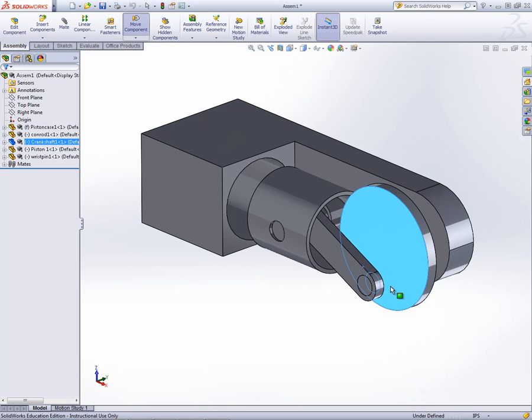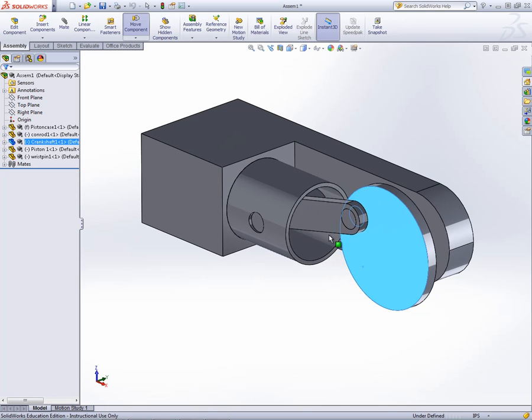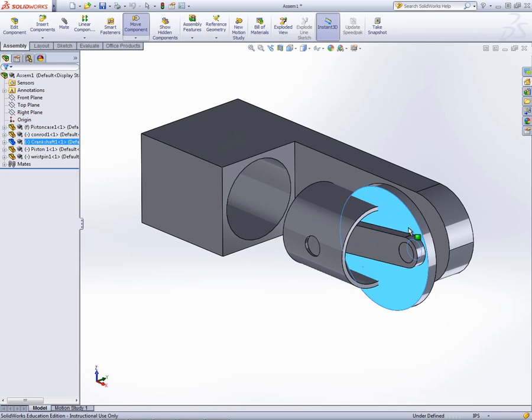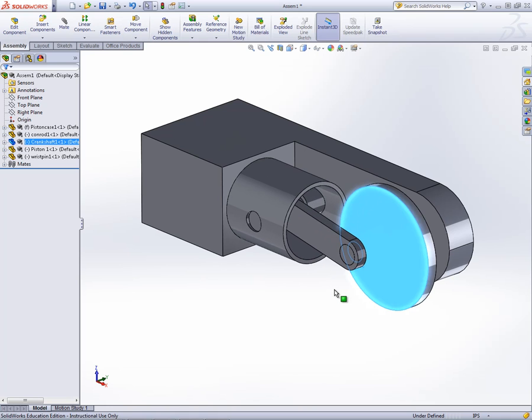So as you look at our assembly, you notice that there is some serious part interference occurring between the piston and the crankshaft. And one quick way to alleviate that is to lengthen the connecting rod. So I'm going to move my cursor out into the work area, left click one time, and what we're going to do is edit the parts while here in the assembly.